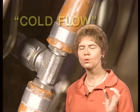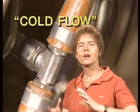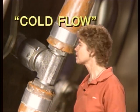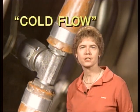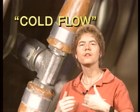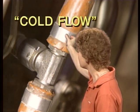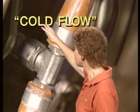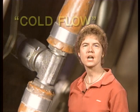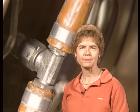Now, a term that is associated with flexible hose is the term cold flow. Cold flow is what you get with the deep permanent impressions that you have in a flexible hose, and those permanent impressions are produced by the pressure of hose clamps or supports, and that deep indentation is called cold flow, and it is associated with rubber hose. It is not associated with metal tubing.